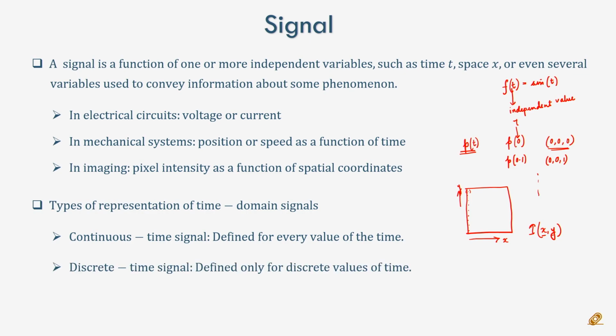So what is a continuous time domain signal? It is a signal which is defined at each and every value of t. For example, suppose V(t) is a voltage signal. Note that t is a real number. It can vary from 0, even negative numbers, but let us start with 0. So it starts from 0 and then you can have any value you want, 0.001, whatever values you want, and it is a continuous variable. If you have a continuous variable and at each and every point of t you have V(t), then we say that it is a continuous time signal.